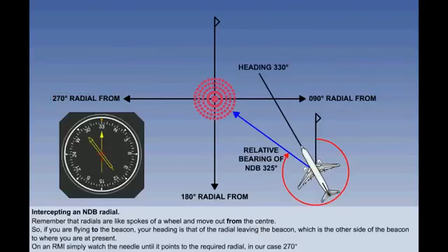If the aircraft has an RMI, your heading is displayed at the top, and the ADF needle points at the NDB, showing the magnetic heading to fly to it. At the start of this sequence, we see that in relation to the aircraft's nose, the NDB is just slightly to the left, so at a relative bearing of about 325 degrees, which is not shown on the RMI.